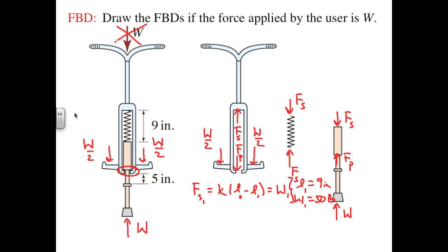Also per the specifications in the problem statement, at a weight of 200 pounds, the spring is fully compressed, meaning the housing is now on the verge of making contact with the step built into the shaft supporting the piston. The significance of that is it tells us that the stretched length under this condition is 9 inches minus 5 inches, or 4 inches.